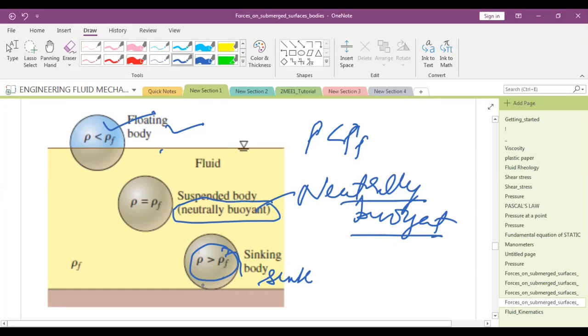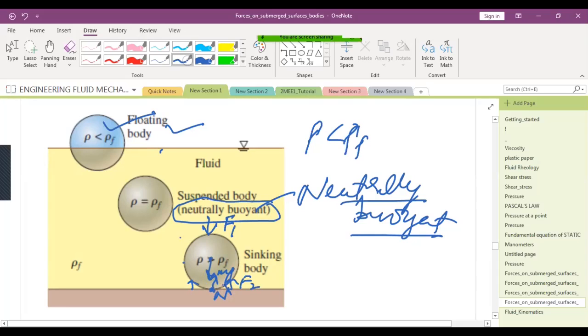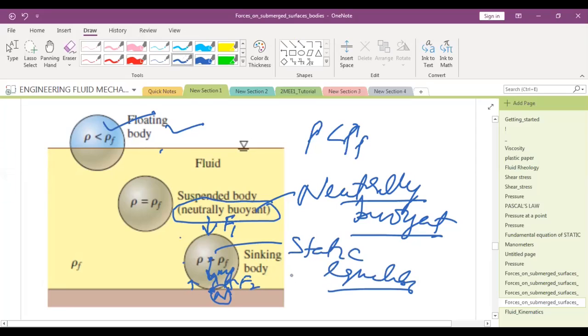तो इसको कौन कौन सी फोर्सेस सपोर्ट कर रही होंगी? सर एक इसका खुद का वेट होगा और एक फ्लूइड की तरफ से डाउनवर्ड डायरेक्शन देखो। एक तो mg इसको नीचे लग रहा है, ठीक है, इस फेस पे कुछ प्रेशर फोर्स लग रही होगी F1, और यहां पे प्रेशर फोर्स लग रही होगी F2, और इसका नॉर्मल रिएक्शन भी लग रहा होगा N। यस सर, ठीक है ना? तो ये N इसको यहां पे बैलेंस कर रहा है क्योंकि दिस इज इन स्टैटिक इक्विलिब्रियम। इसका मतलब क्या हुआ? सम ऑफ ऑल फोर्सेस शुड इक्वल टू 0। तो उसका यही मतलब हुआ कि buoyant force प्लस दिस रिएक्शन फोर्स बोथ आर बैलेंसिंग दिस mg मास। यानी क्लियर है? किसी को कोई भी डाउट? यानी क्लियर?